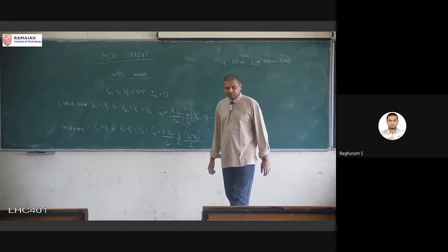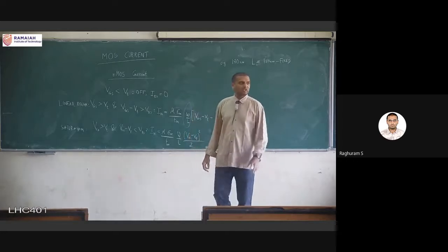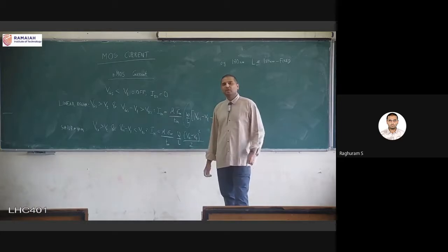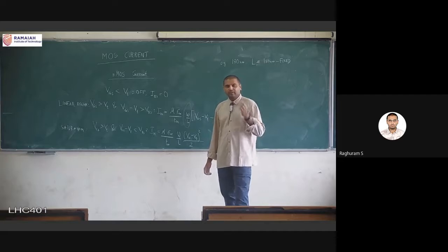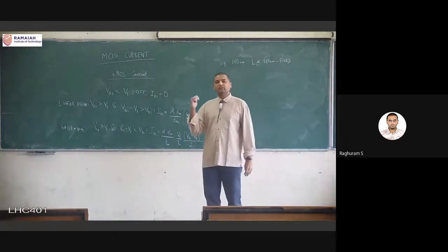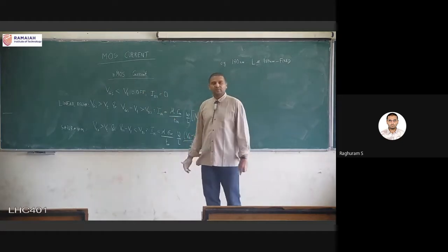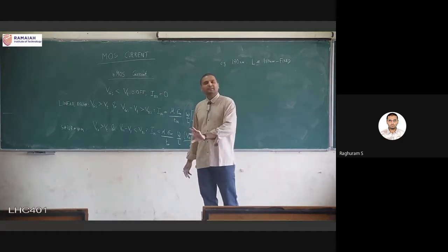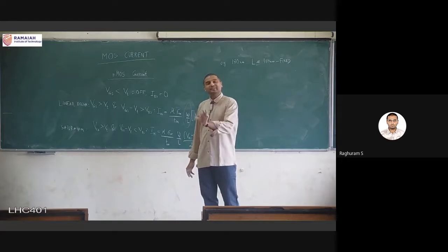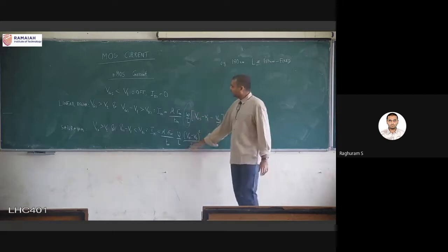What that means is, at that point of time or in that particular technology, because of budget constraints or technological constraints, we are not able to make anything lesser than 180 nanometer. 180 nanometer is the smallest I can make. Now, nobody is stopping you from going from L equal to 180 to L equal to 360. Suppose you are working in 180 nanometer technology, it is possible to make a transistor with 360 nanometer length. Nobody will object. But look at these two equations, both of them.